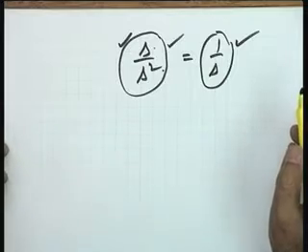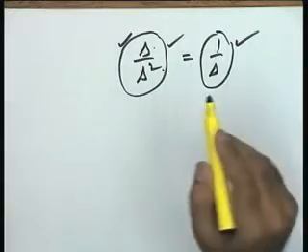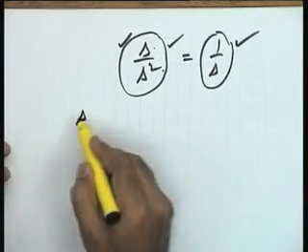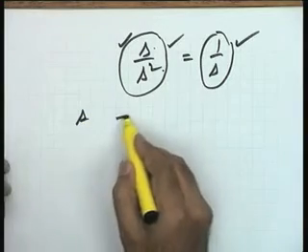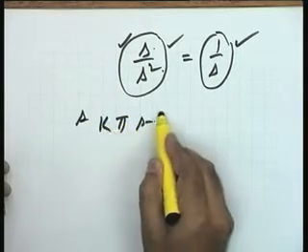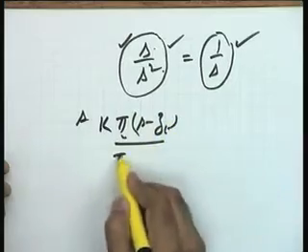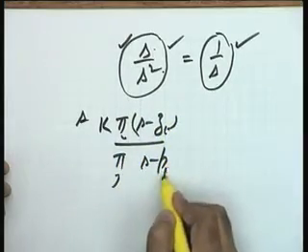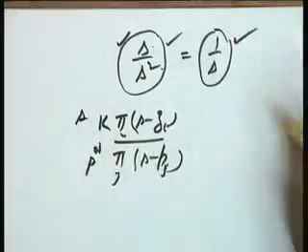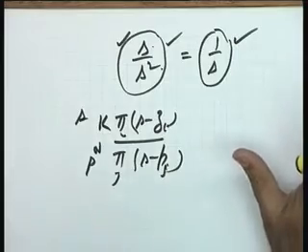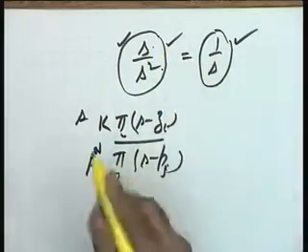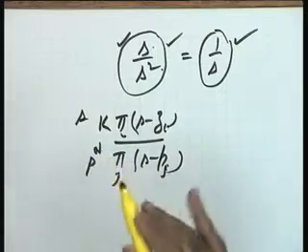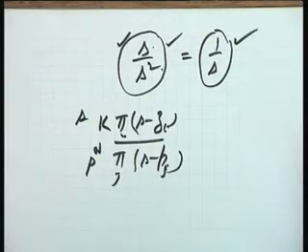If there is a negative value of n2, it means there is a numerator in the s, that is, there is a pole in the s. So, what I want is this: the transfer function which you have written is after all possible pole-zero cancellations have taken place. I am not retaining any pole over here. This final form, this n number, has come after all cancellations have taken place.